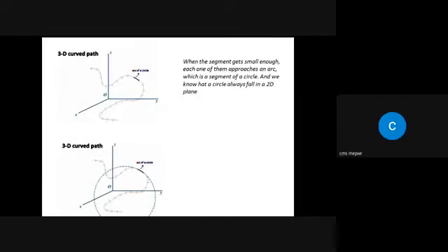Okay, now consider we are having this arc. So if you extend this arc like this, if you continue like this, finally you will get a circle like this, right? Now in this case, the circle that we got, this portion of arc, is in the YZ plane. So that's why we got a clear circle, and it appears in circular shape from the front, right?